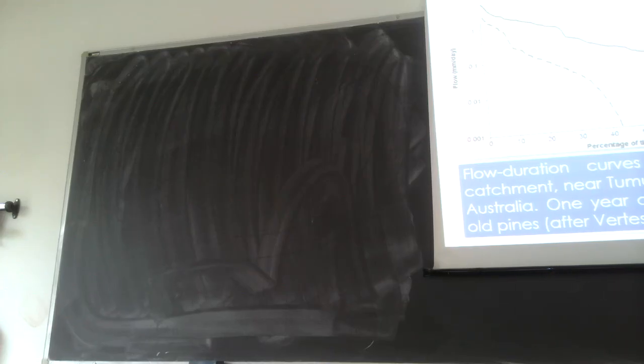Which one can cause flood risk? These two graphs. Very good. If you're concerned about flood risk, having forests is good. Normally, they slow down the catchment response. Normally they increase the infiltration, so having trees instead of pasture is definitely better for flood control problems.